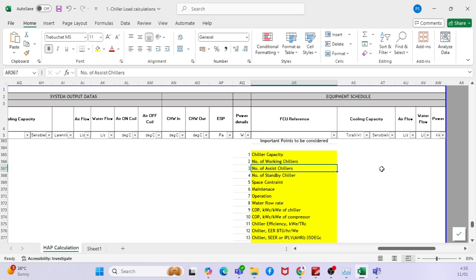That is one reason why you size even the standby chiller to the same capacity as the duty chiller. Now it makes sense. For example, if the load is 2,800 and we size for 3 duty plus the standby, it would still be 1,000 chillers rather than a lower capacity or a higher capacity chiller. Clear. So this is the understanding of the chiller, how we do the selection.